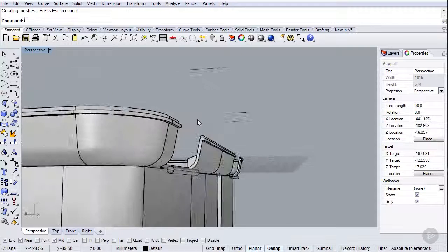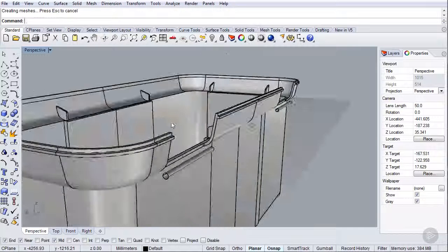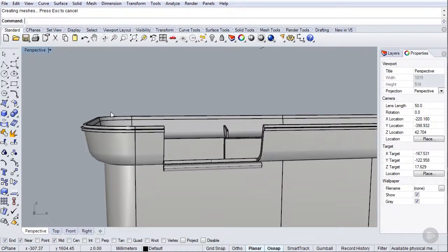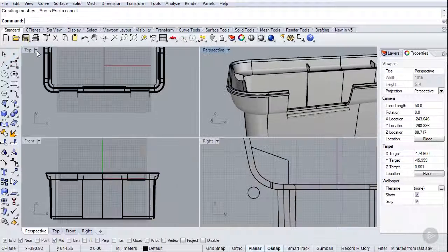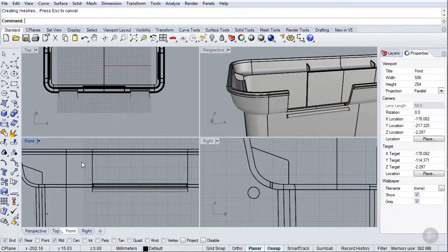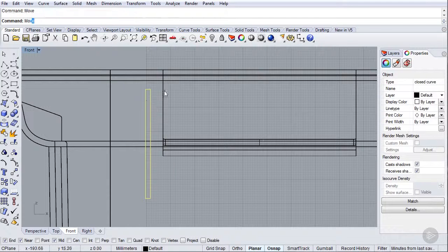So as you can see, these tubes are kind of floating in fresh air right now. So what we now need to build are a couple of extra pieces. It's actually just going to be some ribs that sit on the outside. So we'll start to build those now. We can use another rectangle here. This one's going to have a 2 mil thickness. And it's going to move from this end to this end.